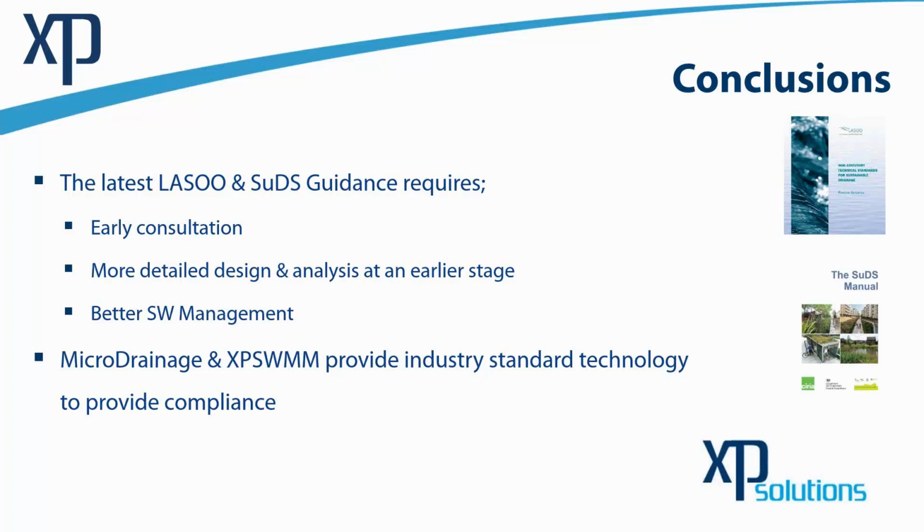Yeah, one approach. Robert is asking about the upper area, if it had been impermeable or greenfield. It's been mixed, so we can create land uses and we can give them certain numbers if there is any infiltration or not. For my land use, I completely ignored the infiltration, so all the runoff which was falling on it was running off, right? But in real life, you can add some infiltration if you want. Yeah, and if it was a mixed use, so maybe it was farmland or something like that, we could incorporate initial losses. Correct. And continuous losses, yes. Exactly, continuous losses. We can incorporate ground saturation as well.